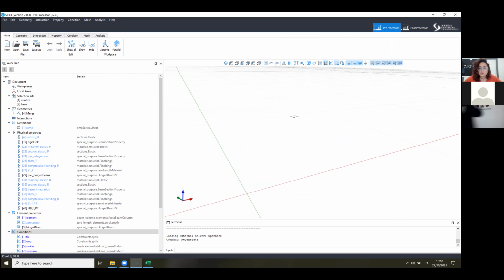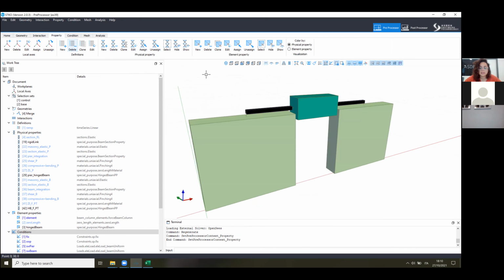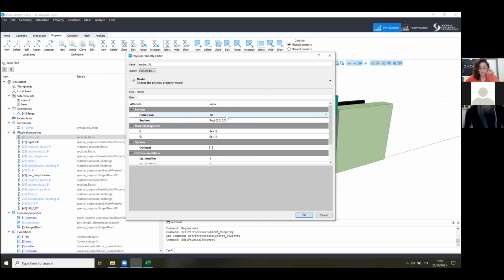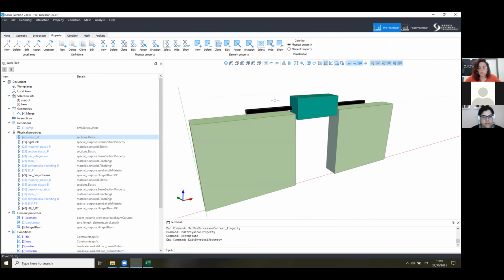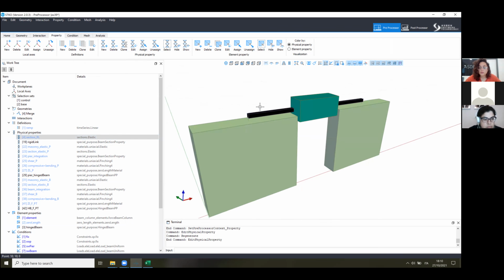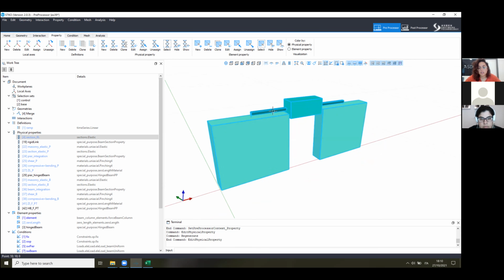Another way to do this is to apply a very rigid beam element to the element that connects the two elements. So we created an elastic section, which is really small. Its geometry does not matter. And we applied a very, very high stiffness to the elastic section in order to mimic the presence of a rigid link. So this can also be another approach, and it can be useful if you know exactly what rigidity you want to give to that link, so if you want to apply a specific stiffness to that link.